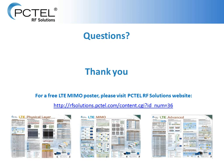Another question, how does the scanner know of cell loading in the network? What it does is when you look at the RSRQ, you're actually looking at the power in each one of those resource elements. So you can indicate that you have higher loading based on an RSRQ value. It's not going to give you a detailed analysis of what that loading is, because you really don't have a session with the tower or with the base station. So you can get an indication, based on all these values, of what's going on in the network with these parameters that we measure.